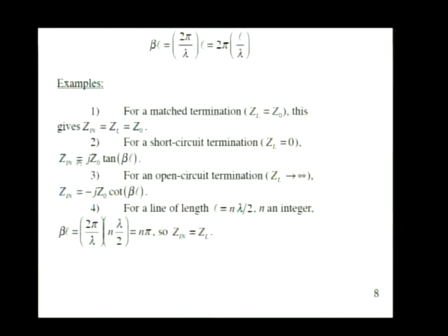And it's Z0 times a tangent function, and that tangent function is a pretty wild-looking function. Remember, the tangent function goes from minus infinity to plus infinity periodically with a period of pi for its argument, and so on and so forth. So what I'm going to do next time is I'll take up with some sketches of what those functions for input impedance look like for open circuit and short circuit terminations.